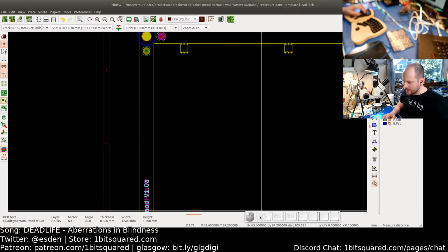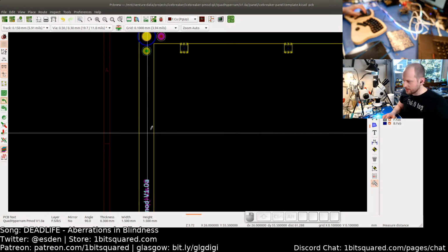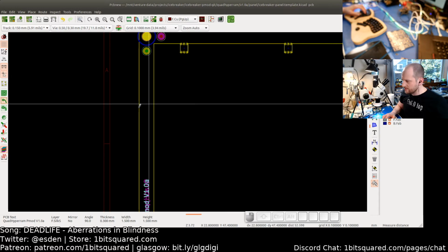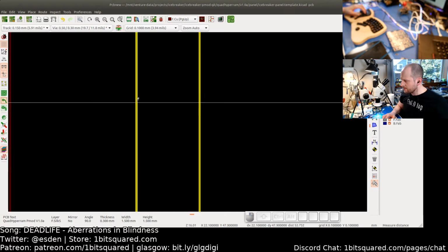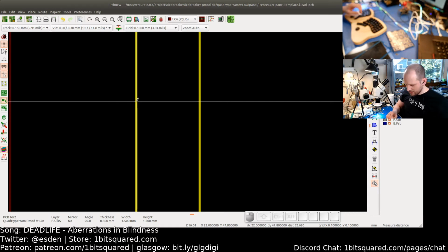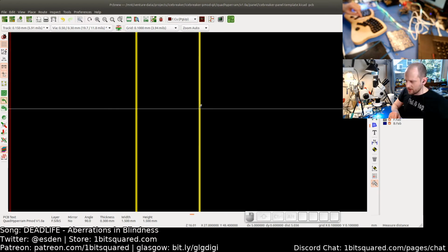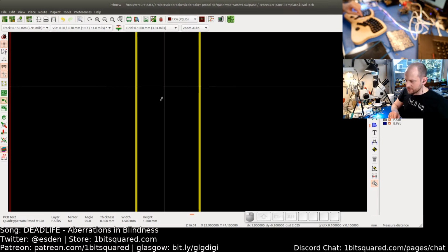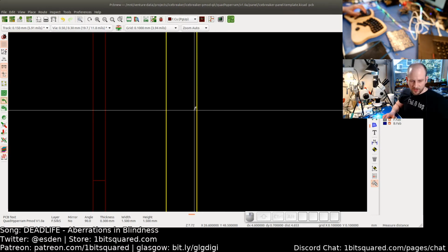Traditionally, you were using this entry here, which is the delta distance. So here on the bottom, you see maybe my mouse. On the bottom here of the window, you have the delta. And you can use a view like this, hover with the cursor in a place, press space, and the delta will reset. You saw the delta reset on the bottom there? And then you can move to a different spot and see the distance, as well as distance in X and distance in Y. So these can be used for measuring distances between places. That's the traditional way of doing this.